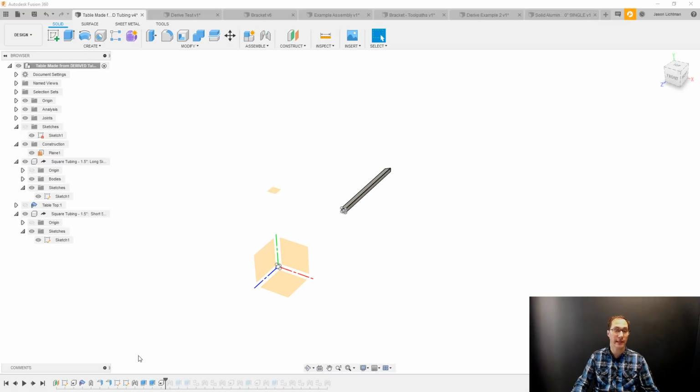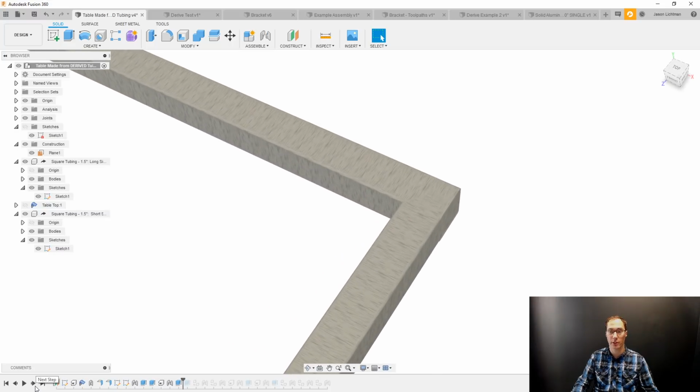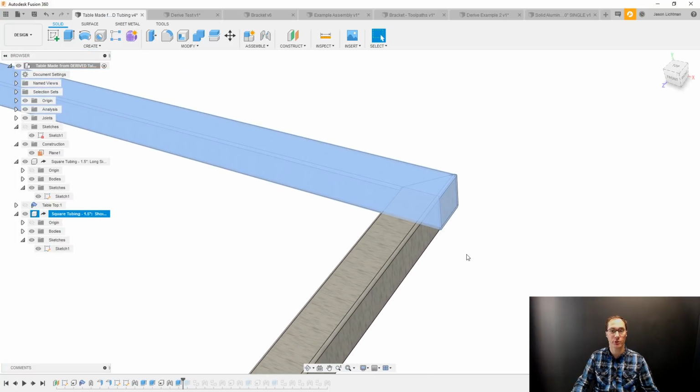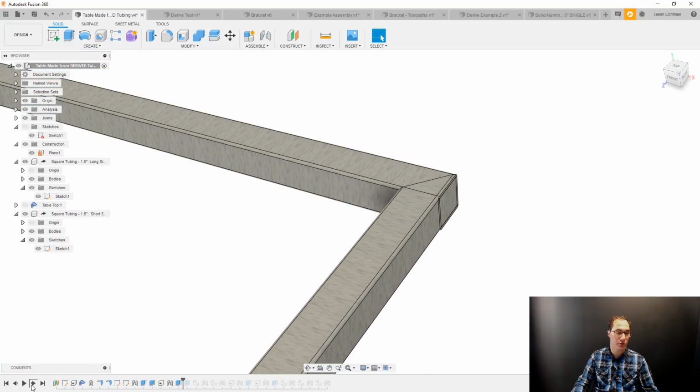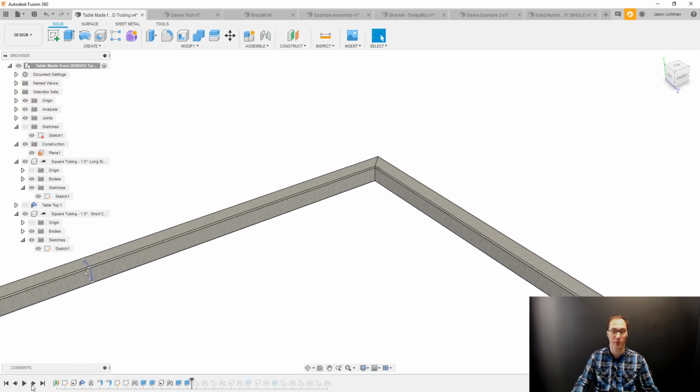So the next thing that happens is I made another joint using that second sketch. And then I did another extrude, and then another extrude to chop off or miter the corner. You didn't see that. Let me go back one more step. Now with the graphics updating, you can see that I have an overlap. If I double click this, you'll see that I have an interference between them. So then I do another extrude cut. Now that interference is gone and I have a nice perfect joint.